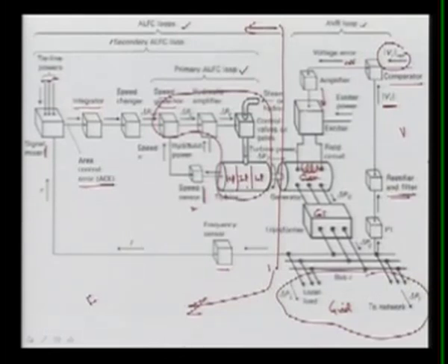So we can also sometimes give some auxiliary signals to the exciter. It is not only voltage, we can give some other signal, we will see later on. Then here we can give some auxiliary signal. Now this exciter, as you know, also requires some power, and that power basically comes from the rotor. So normally this exciter is rotated through the rotating body of the turbine here. So we give some input power and we will see the model.